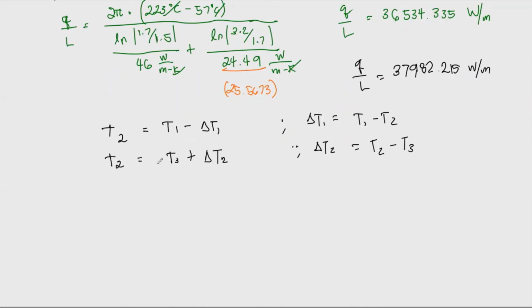Okay, so with that, using the equations that we have here, the total heat is actually equal to the heat contribution for each one, because they are adjacent to each other. So in this case, Qt is equal to Q1. We could just simply say that the change in temperature for the first one, or the steel, would be equal to the resistance offered by the steel multiplied with the whole change in temperature, then divided by the total resistance, that is R1 plus R2.